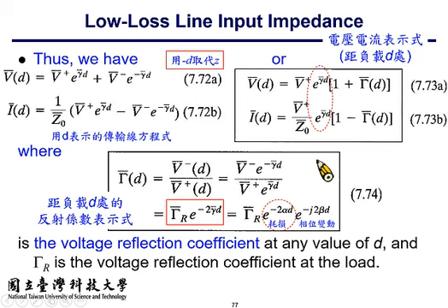这边课本标伽马 R 了，alright。So in this slide, we try to discuss the relationship between the reflection coefficient gamma at specified position location D and the reflection coefficient at the load, which is gamma R. So gamma D, by definition, is V minus at D over V plus at D, which can be replaced with V minus, as I already drew on the board.